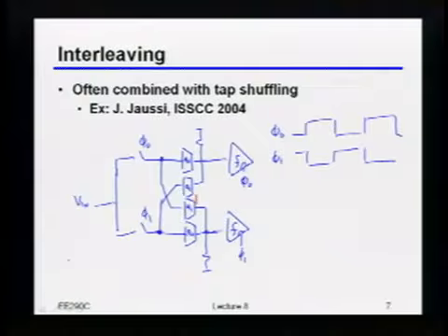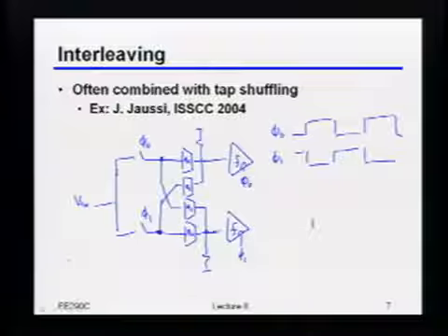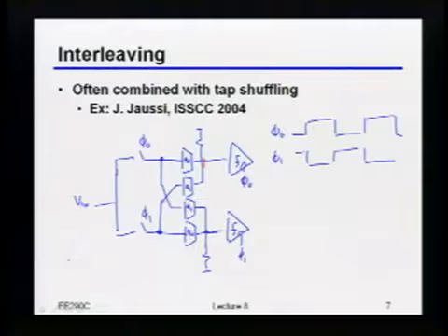As an example, in the linear equalizers, that tends to be trickier because setting gains precisely is kind of tricky. But if, in the DFE, I had 2 current steering DACs, and those are largely DC DACs, I can probably design them to match sufficiently well that I wouldn't necessarily have to adapt them individually. Maybe. The key difference is that's outside of the signal path, versus this is all the high-speed stuff in the signal path, and making it match that precisely is probably expensive from a power standpoint. It's a great question. Other questions on this?